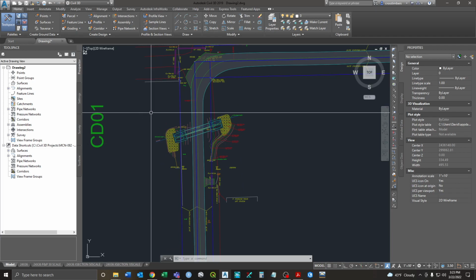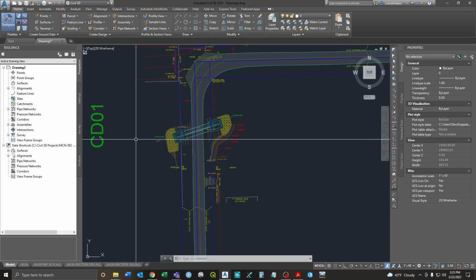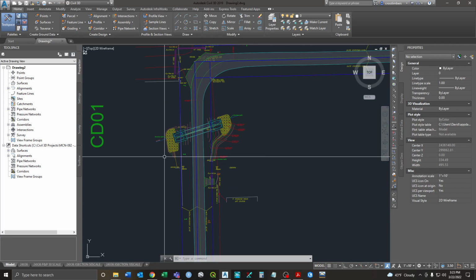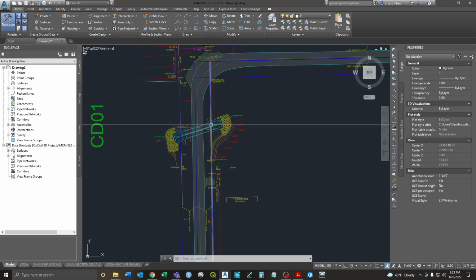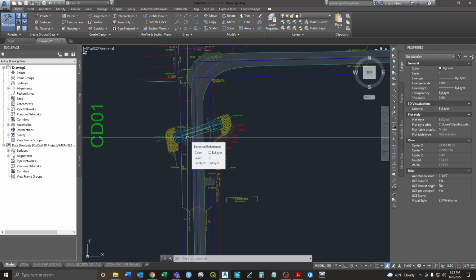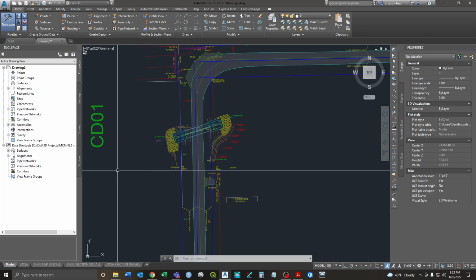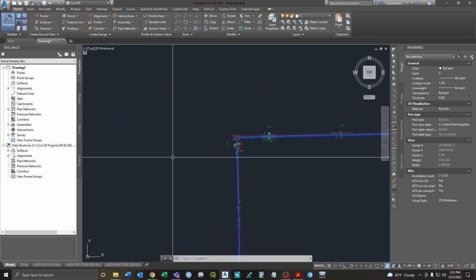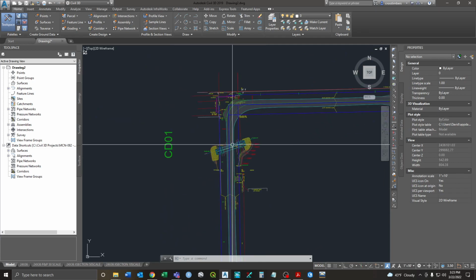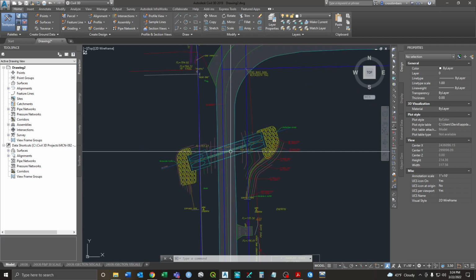And so now that we've created those layers, that's kind of what we want to draw when we do the right of way over here. We want to use that layer, and we can turn it on and off to not get confused, because obviously you're going to be drawing a line from here over here, and it'll get really cluttered if you're just piling them on top of each other. Okay. So if you make independent layers, and then even if you copy them over here, then you can turn that off as needed.